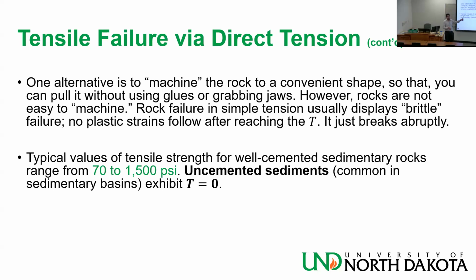Sigma 3 in the far field can be one of the in situ stresses. If I'm near the wellbore, it might be another kind of stress, cylindrical stress, that we are going to learn later. This is a very good point, because I remember in my PhD proposal I had sigma ZZ, for instance, the axial stress, or some weird stresses that we are going to learn later in this module, smaller than minus T. One of my professors, a Chinese professor, told me to change that to sigma 3 so that you are more general.